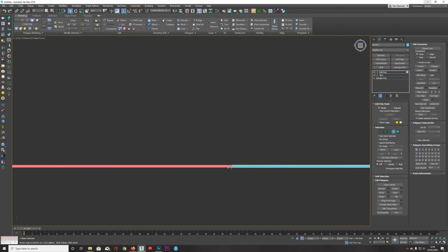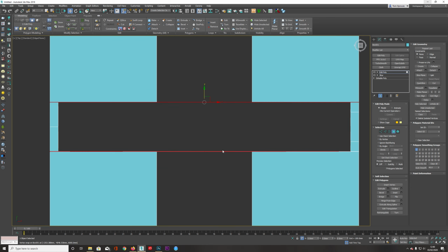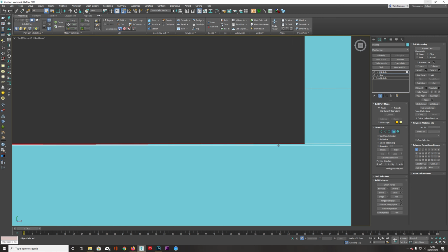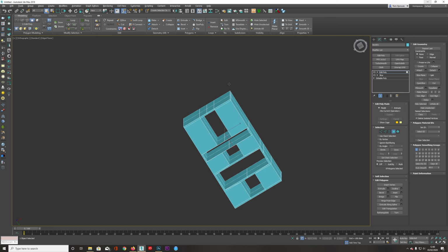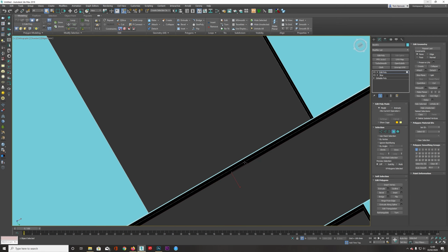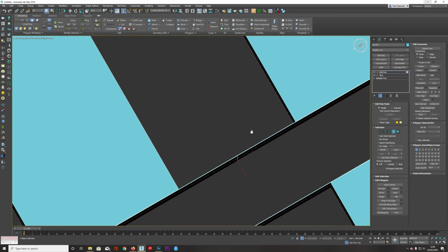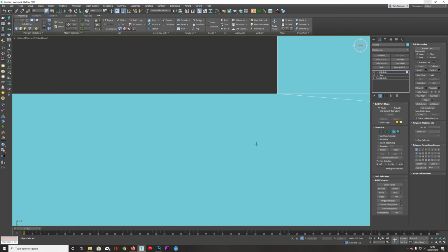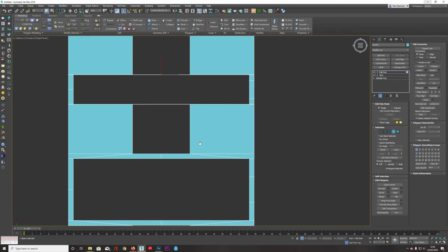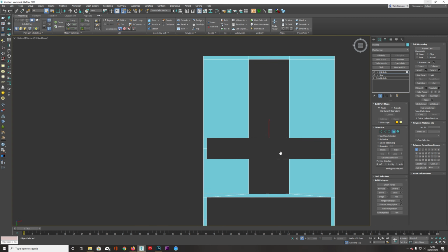I'm going to press Q because I don't want these things to move. See, Q here comes into select object as opposed to this one, which it was on, which is select and move. So now I can select things without fear of anything moving. And I'm going to come into the bottom view, and just press V actually. V, bottom. And then I'm just using the middle mouse wheel here to roll out and in.